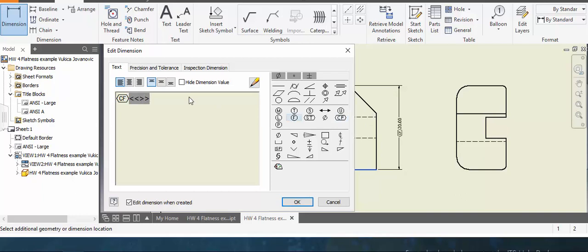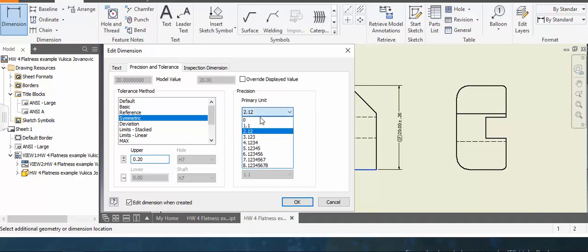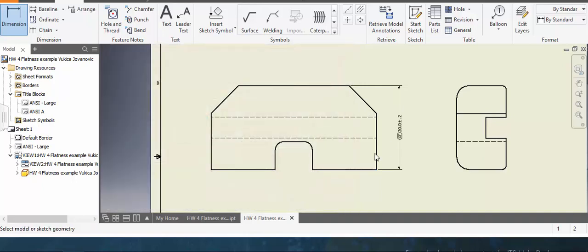Or these I will add. So you see here they also have where you can put some of these conditions, but we can put it outside, or you can put it in the front, like here you see. So here I selected CF, and then I'm going to symmetric, and I will select 0.2, and I can switch the primary unit just to show just a digit or something, point something, and you can select here what is the something you want for the specific reference. And then I will proceed in making these different ones.